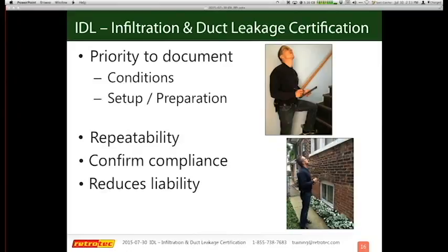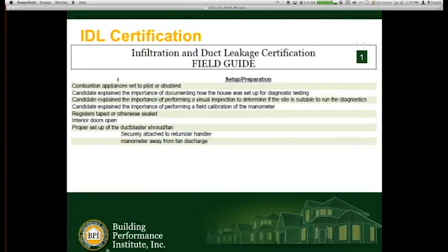And it's really important to walk outside for this kind of test. A lot of people will show up, go inside, and start setting up their test. So I do have some things about the blower door and places you should check. But in general, you want to make sure you evaluate the outside and inside. And for the blower door, the crawl space and attic, and a few other areas that are high priorities that some people just assume are in acceptable conditions.